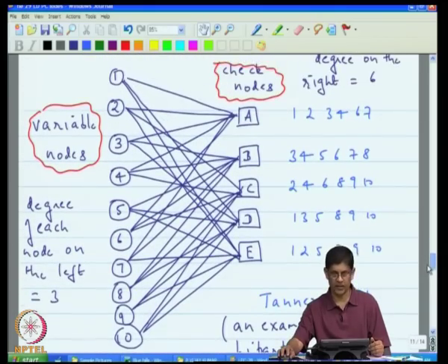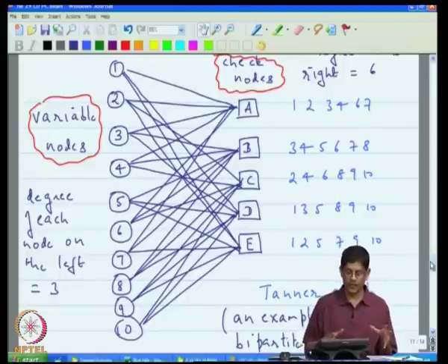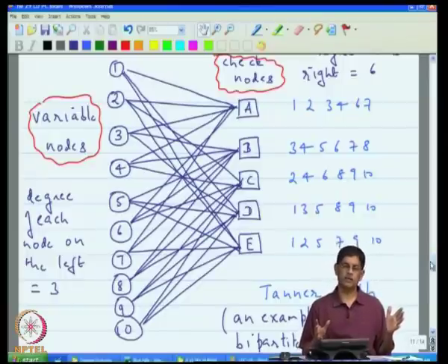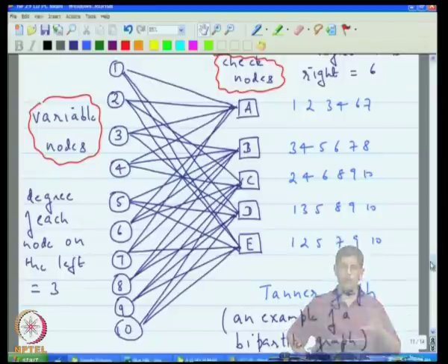Their greatest strength is the ease with which they can be decoded. And now you might think, well, but does that come at a price? To some extent, yes. The answer is yes and no. It depends on what you are looking for. These codes in terms of minimum distance may not always be the best possible code that you can get for that block length. However, they make up for it in performance. It turns out that for practical purposes the performance is pretty good.